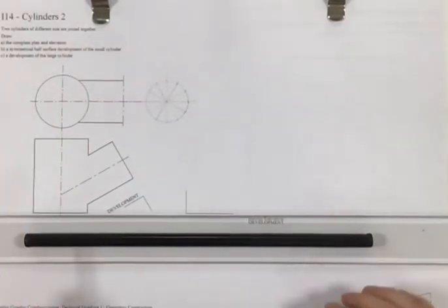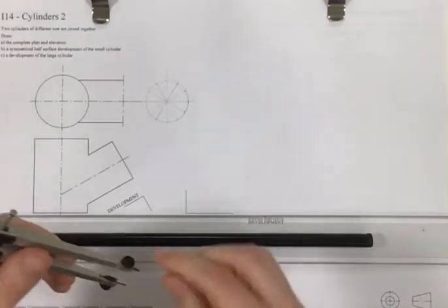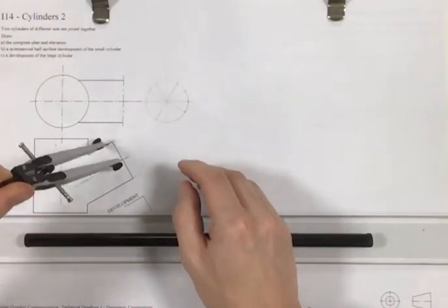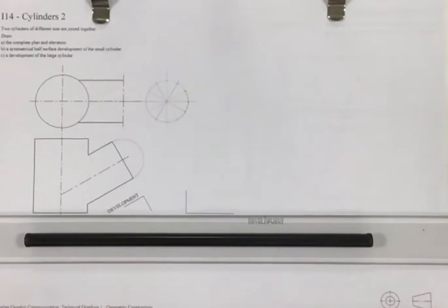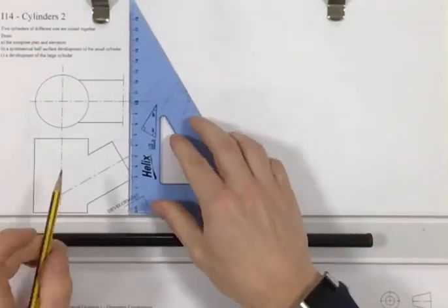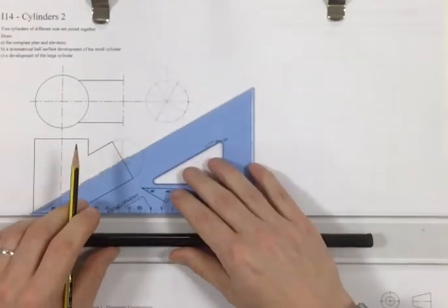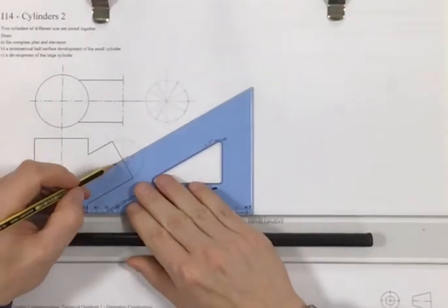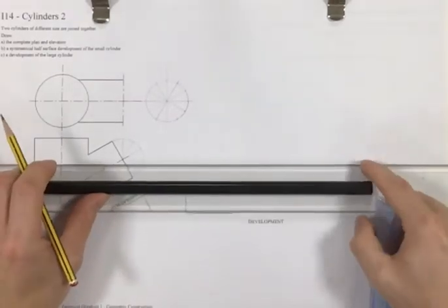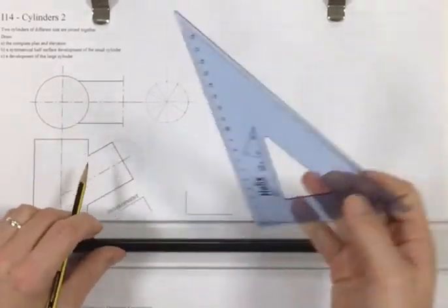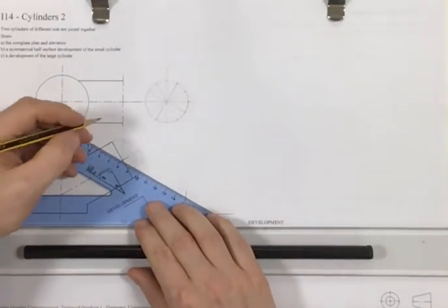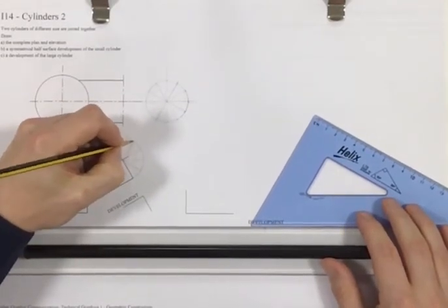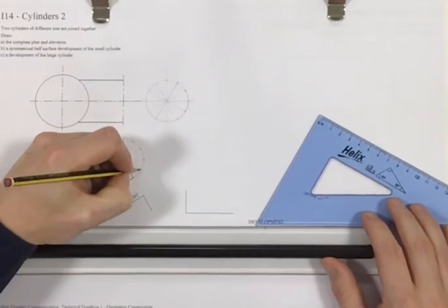It's just to get an idea where the lines cut through the circumference of the circle. The next thing that we want to do, again construction work, is draw a semicircle just on this part of the pipe here, and I'm also going to divide that up into 30-degree segments with the 30-60 set square, just so that I can get the points where the lines cut through the circumference of the circle once again.